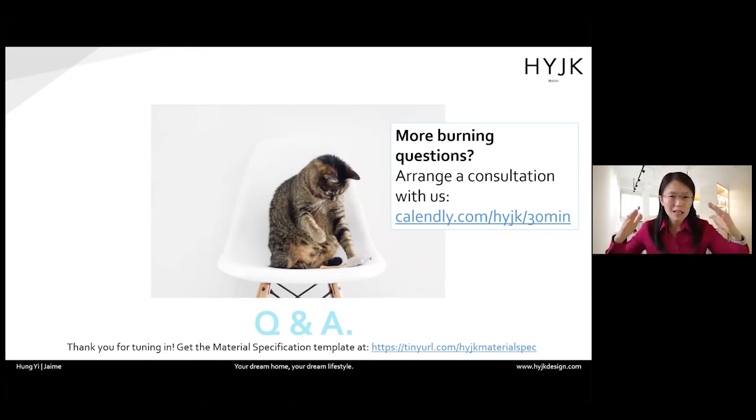It is less likely to warp, which is something that you find problematic in 100% wood. And you will find that it's less problematic with pests, though not 100%. If you have a termite problem, over time, your engineered wood will not be able to escape as well. But there will be a bit more termite resistance. Besides that, in terms of moisture and humidity, expansion and contraction, generally your engineered wood should perform better.